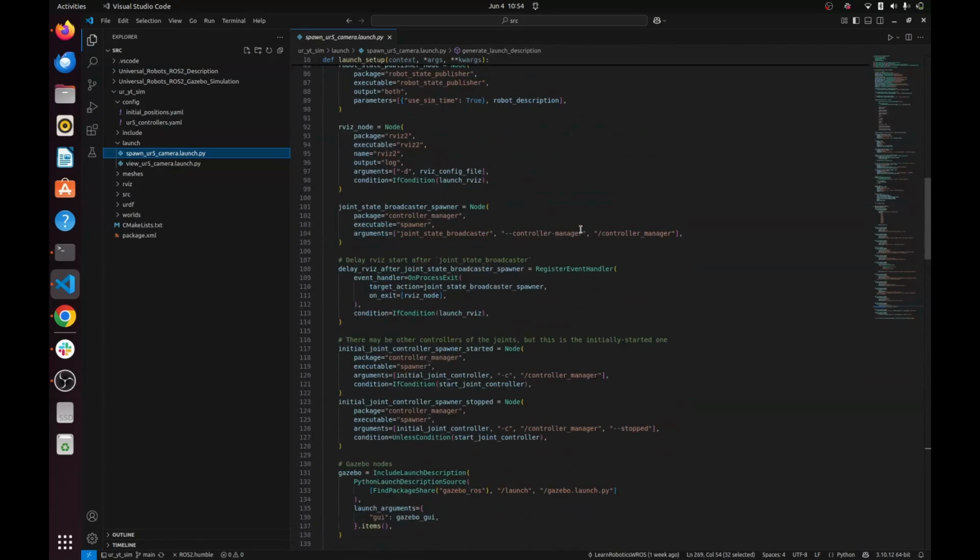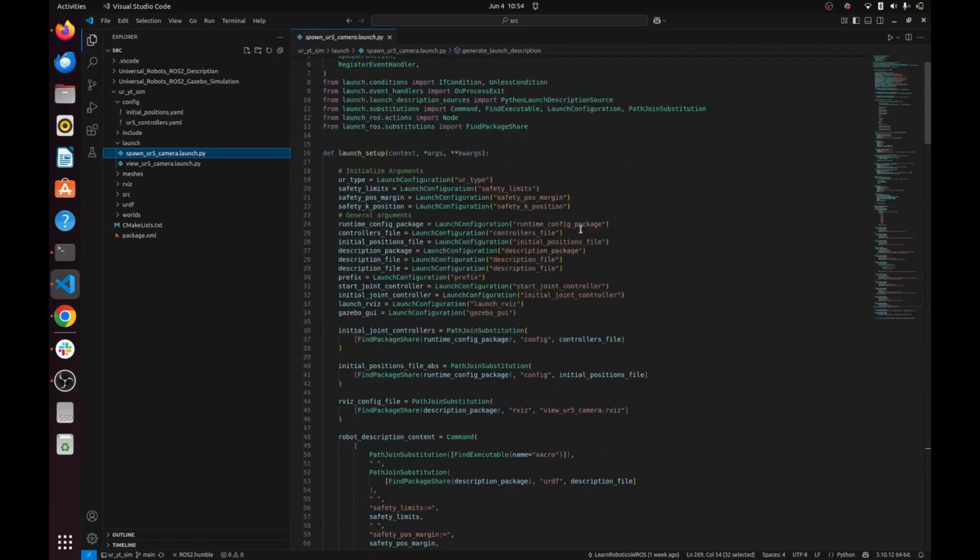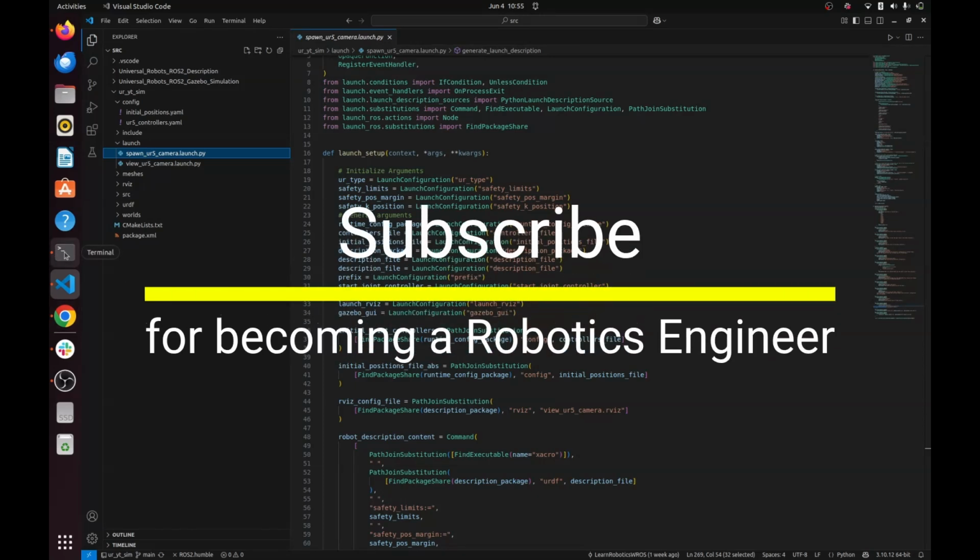Okay, so the most important thing to do now is to set up the environment for running inverse kinematics, right? And to do that, we're going to create a MoveIt configuration package. We have already done it, but let's do it with a Universal Robot without the gripper.